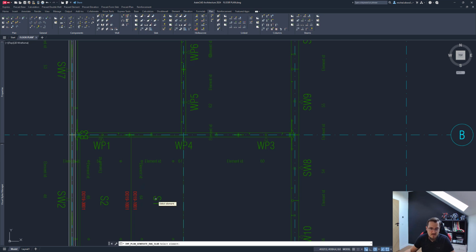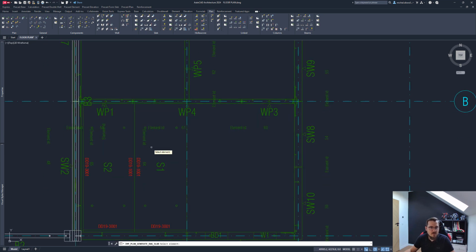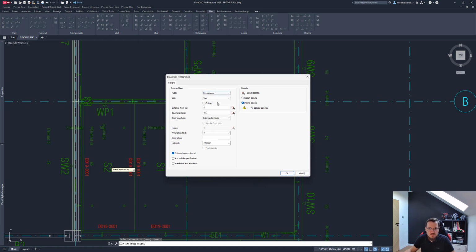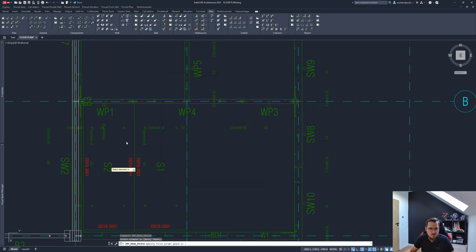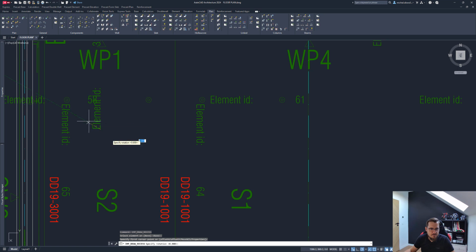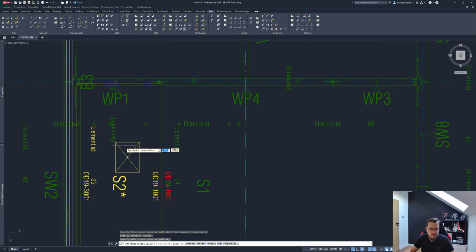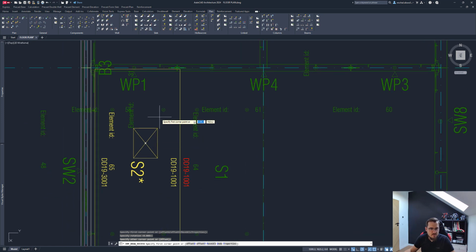You have to click the slab section. One thing we can very quickly do is create an opening in a slab. Let's select, say, this slab. Let's create a cutout, a rectangular opening, say like this dimension.